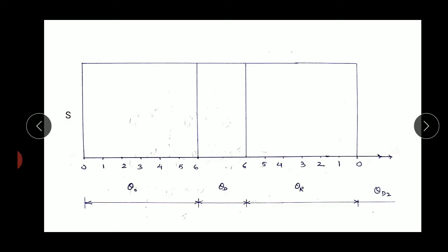During outstroke this much angle is turned, so draw the displacement over here and complete the box. Suppose this is 40 mm, so this is also 40 mm. During the dwell keep it as it is, and during the return stroke, whatever the displacement of the follower during outstroke, the same will be the displacement during return stroke.